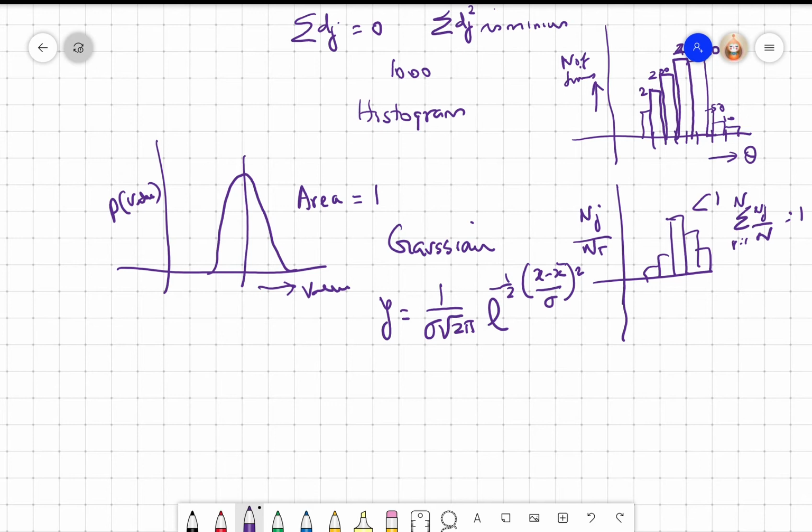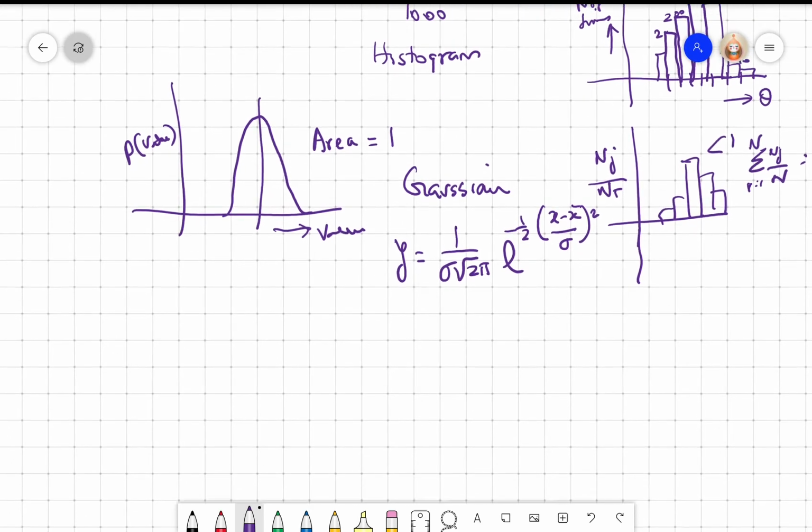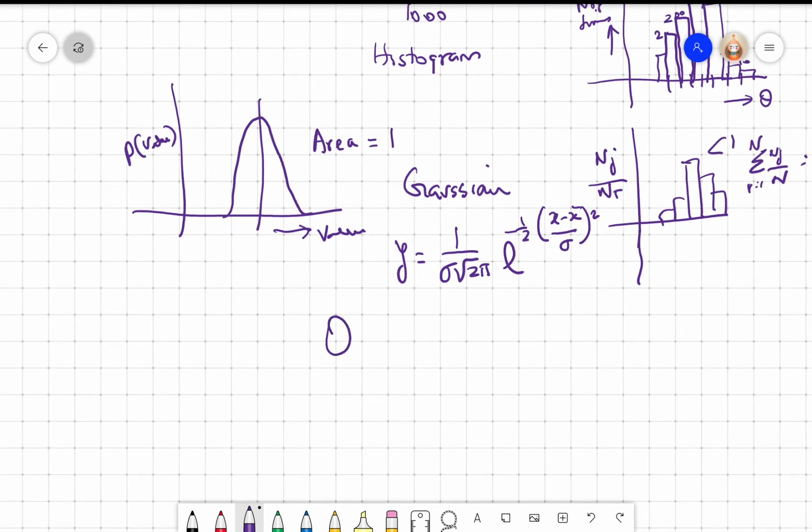We also learned that when we get random errors, we indicate the result as the average value theta bar plus or minus the deviation, right? D can be D max, which is compulsory if you have manufactured things that need to be fitted. Last class we saw that the bearing and the rod in a fan, you have to have maximum deviation specified. Your RMS or standard deviation will not work there.